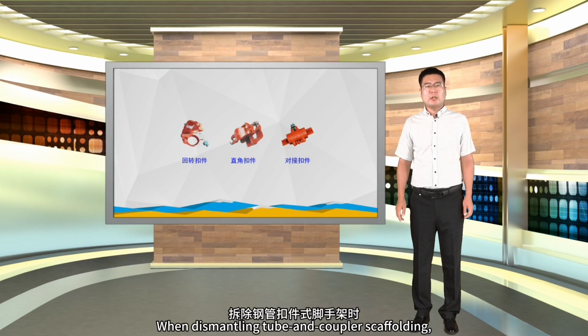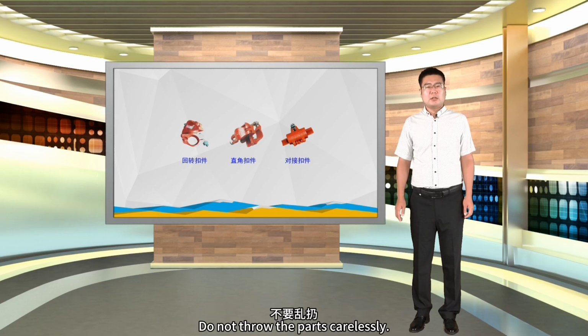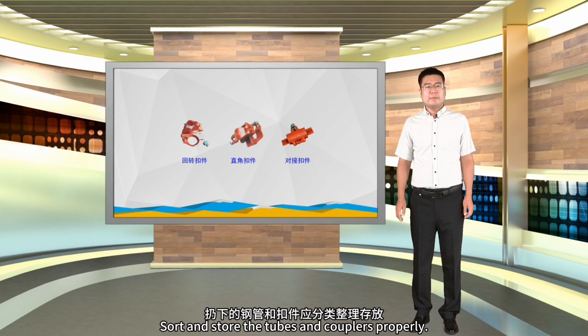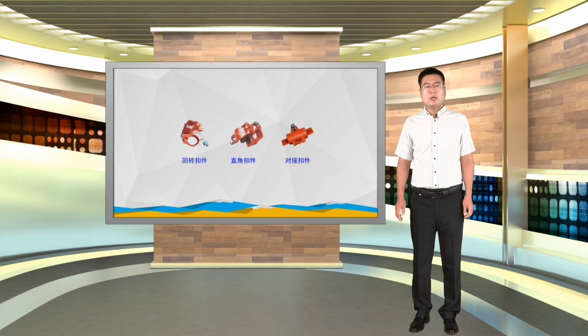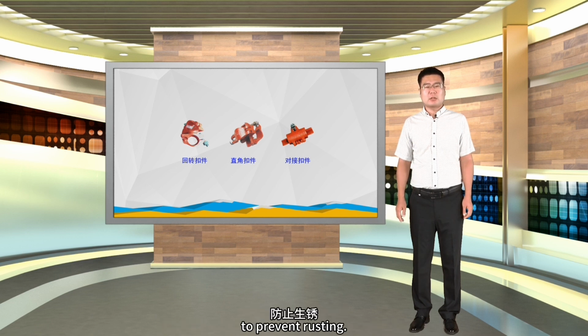When dismantling tube and coupler scaffolding, take it down in order from top to bottom. Do not throw the parts carelessly. Sort and store the tubes and couplers properly. Repair any damaged components. Scaffold tubes should be repainted once a year to prevent rusting.